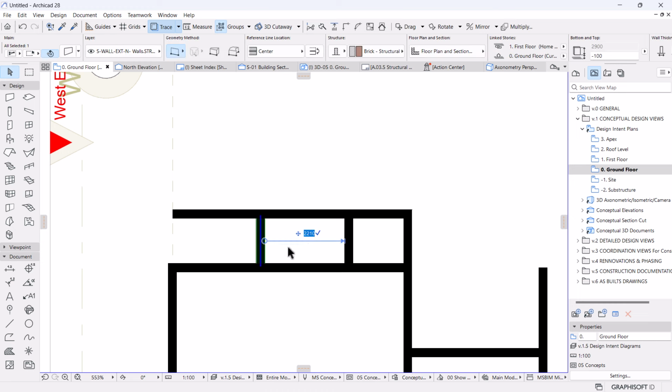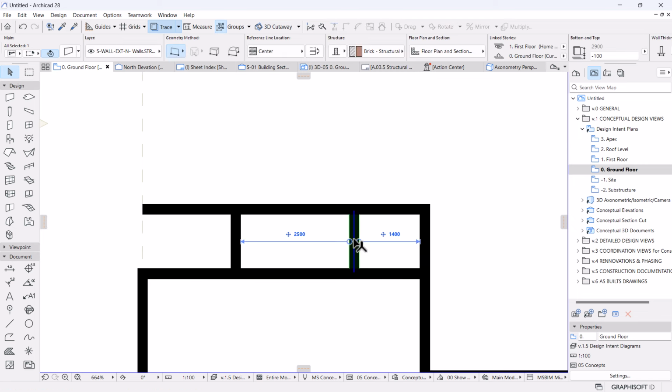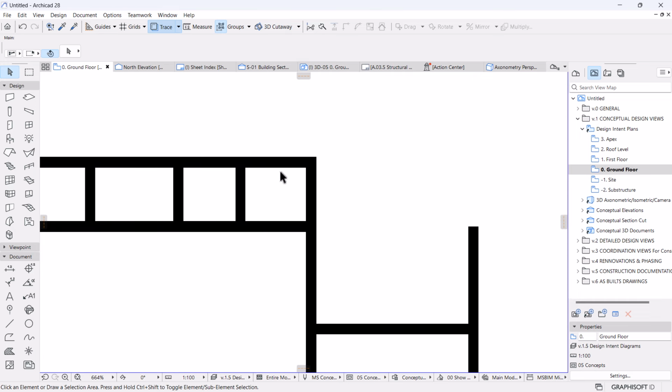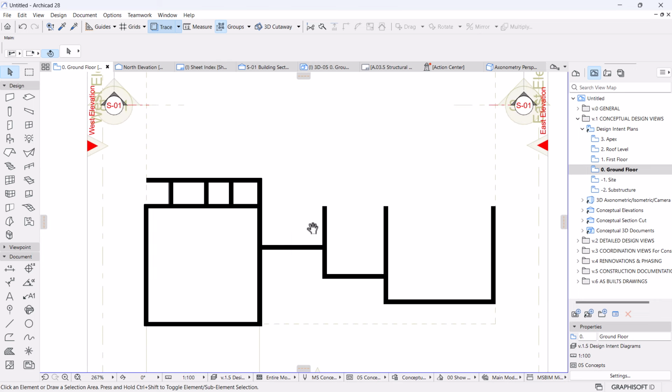So I can even increase the width to be 2.5 because I'll need an extra wall here of 1.2. Let's make sure it's 1.2, and then this will be where the toilet will be positioned. I think we'll need a leg room of maybe 1.8. Oh, sorry about that. I should be doing on this one 1.8 like that. Perfect. So we have a lobby that we have a door to, that will transition to the staff room, to the powder room, and then we have the toilet.